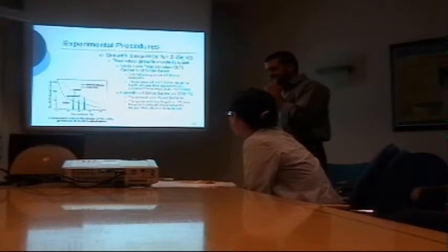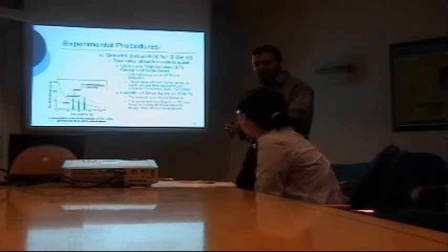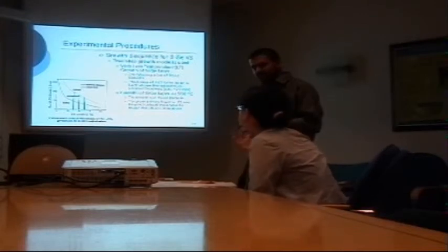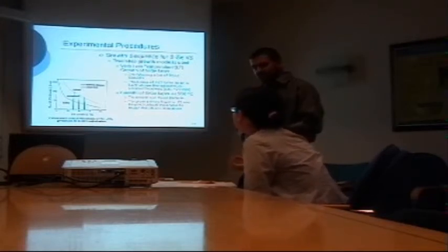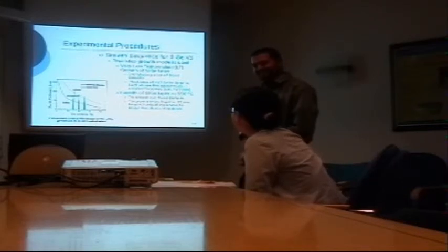At very low temperature, I think the atoms which come to the surface have very low mobility, so there must be disordered growth. Due to this disordered growth, there can be some vacancies or interstitial atoms. So these are the point defects, I think. So because of the low energy, only point defects can happen rather than line defects? Can be.